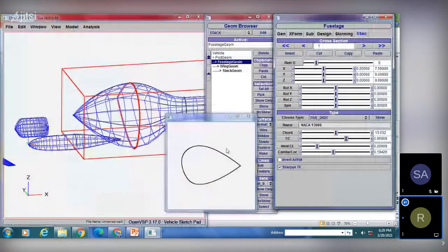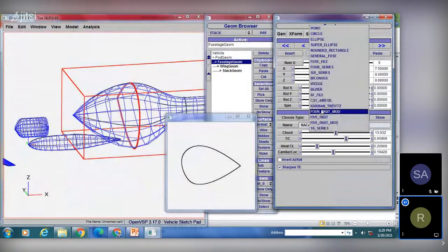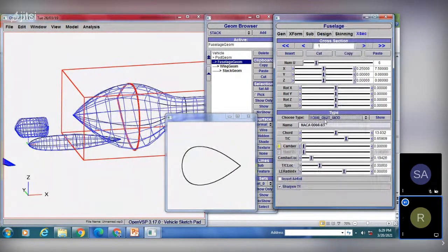Here we also have the NACA 4 and 5 series modified aerofoil. Here we can see the modified aerofoil provides additional control over the leading edge radius index and the location of maximum thickness. The naming convention follows the usual method for 4 and 5 series aerofoil with the extension of two additional digits indicating these new values. The leading edge radius index ranges from 0 for sharp to 9 for semicircular, with a default of 6 corresponding to the traditional series.